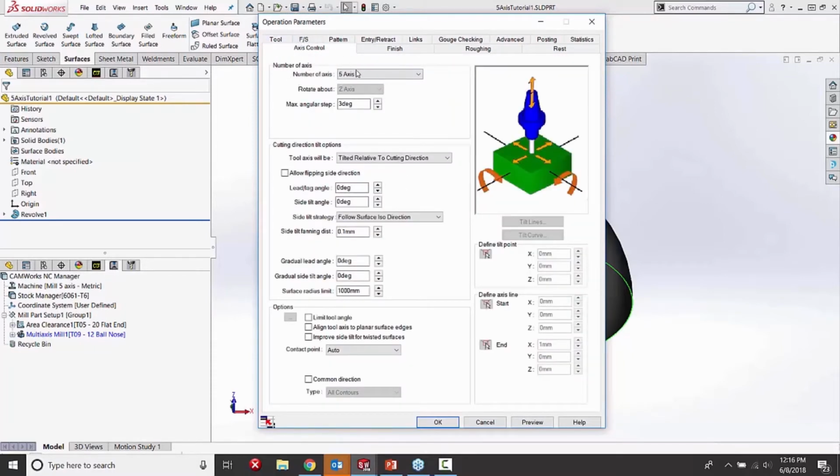That's always where I start, because we need to be very specific here about how many axes we are actually allowing in the motion of this toolpath. It's not always true that on a multi-surface feature, oh, we've got a 5-axis machine, just let all 5 axes have at it. In this case we are, but that's why it's important to jump to this tab first and really, don't let your machine run wild. You need to exert some control and some intelligence over it and really specify what you're trying to let it do.